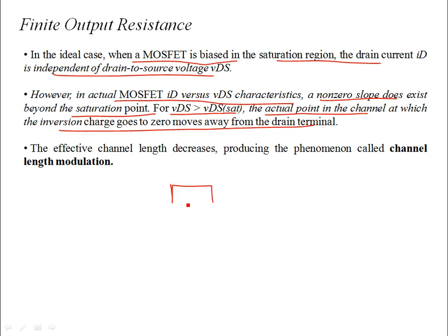If you consider a two-dimensional cross-sectional view of the MOSFET, you have the gate metal over here. This could be aluminum or a polycrystalline heavily doped silicon material. Then you are having an oxide, which could be silicon dioxide, any oxide insulator, which is going to offer insulation between the gate and the substrate body.